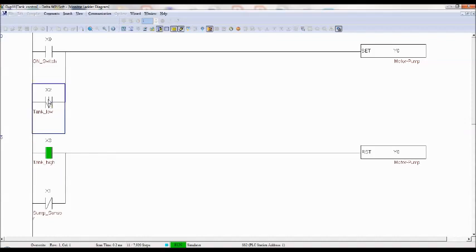When draining starts, when the water level starts decreasing, then the high level sensor will be off. And then when the tank is completely empty, this sensor is going to be off. At that time the motor will be on again. So this will be repeated. This is what the controller automatically does, monitoring the water level in the water tank. That means it won't make the water tank empty, so it is always going to be full. That is what the control is.